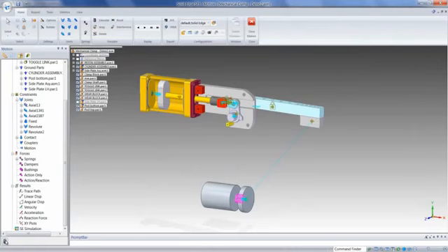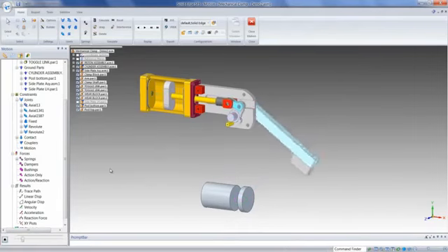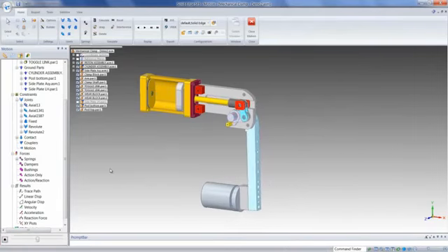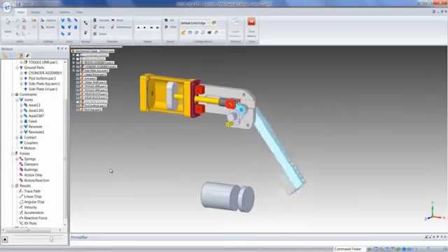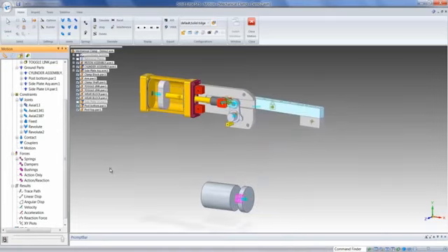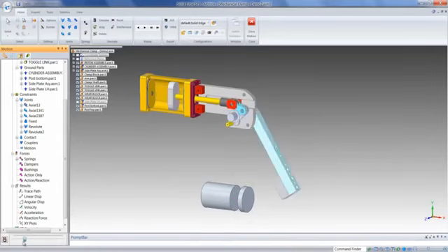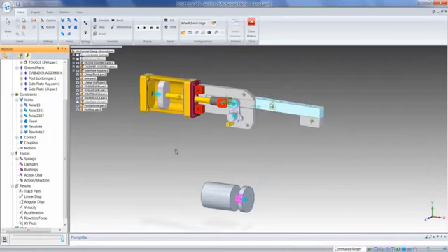We'll go ahead and simulate now with our contact in place. Now that our simulation is running correctly, we'll go ahead and plot the input force. A great feature of Dynamic Designer is to be able to reverse engineer inputs. For example, we can plot the required actuator input force needed to cycle this mechanism. The same is true for motors.